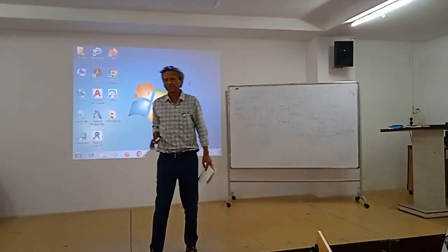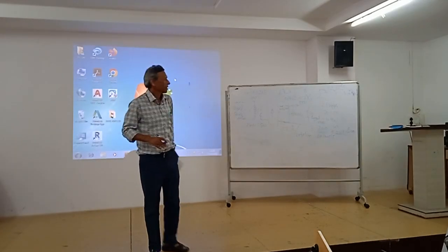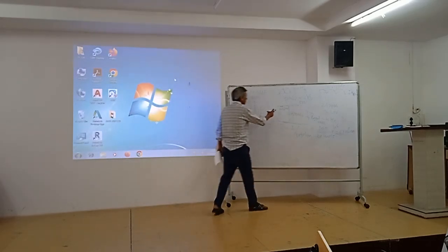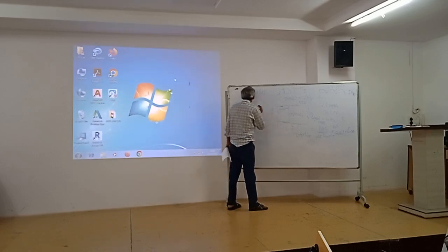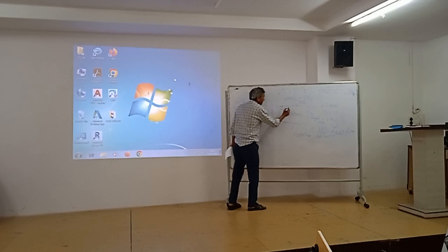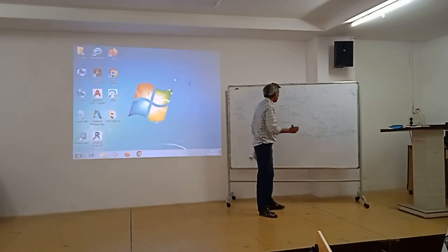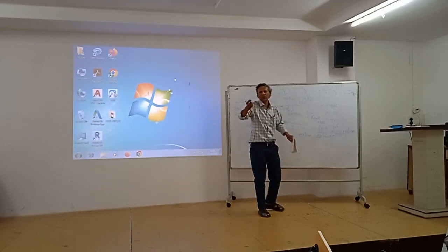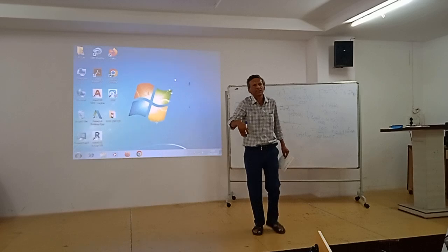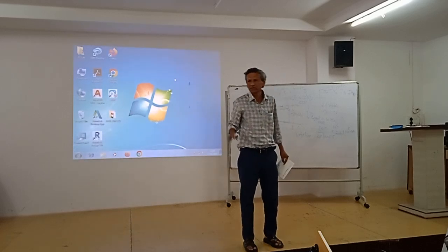Current restricted. Now 10 ohm I am writing, it can be 5 ohm, whatever. Now whenever I will close this, this will come into the picture, which will restrict this current, and as capacitor will charge for only few milliseconds, the current inrush will be there, then the current will be reduced.